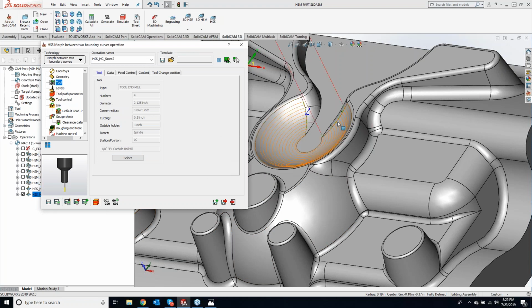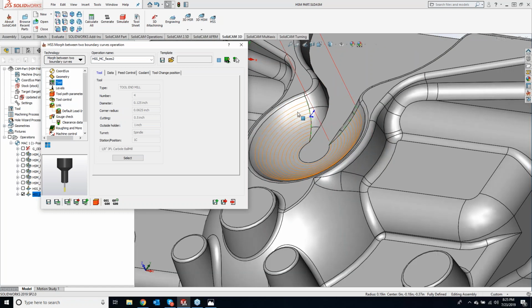And I always want to get a tool path to kind of see what I'm looking at. I don't want to come in here and start fine tuning stuff if I have a huge rat's nest in there. But I can see I have a very good tool path. I got good control, and I'm just coming in there, just doing a zigzag, working its way back and forth.